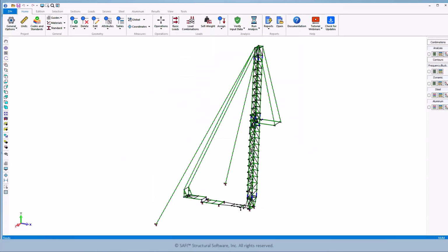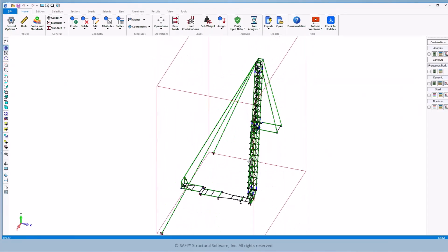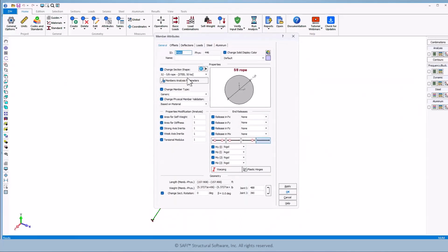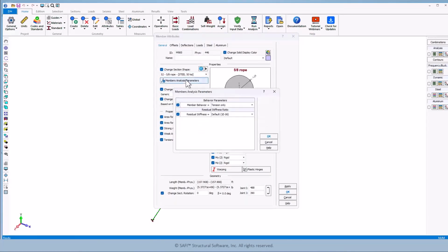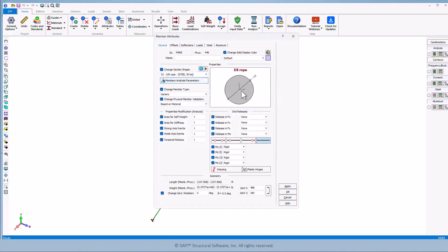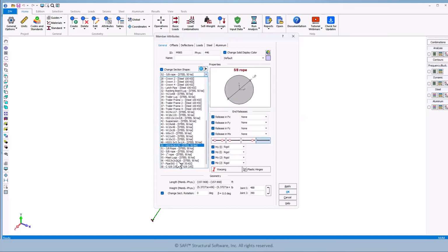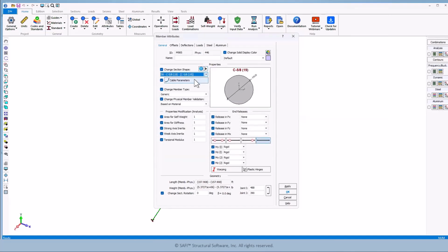Depending on the type of structure you're modeling, PSE also includes full support for cable elements. There are two types available. The first is a linear cable, which behaves essentially like a tension-only member, straightforward to define and well-suited for most guide or braced configurations. The second is a catenary cable, which accounts for the physical sag of the cable under its own weight and any applied pretension.